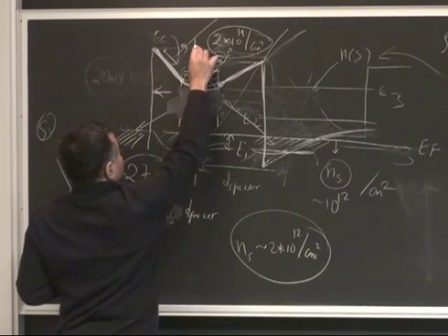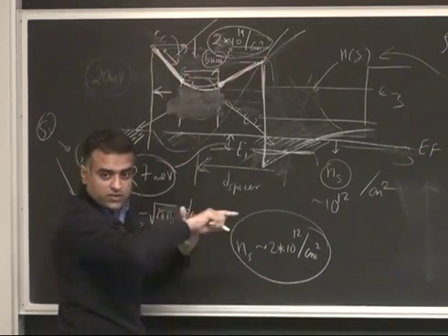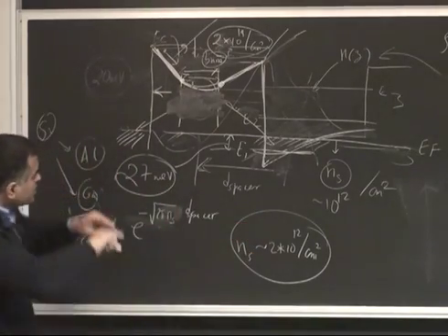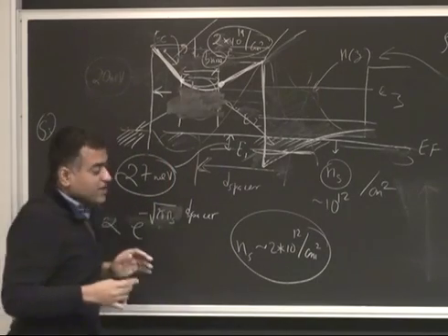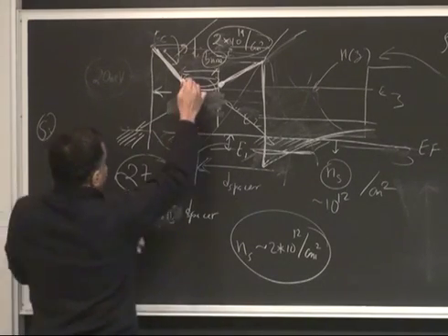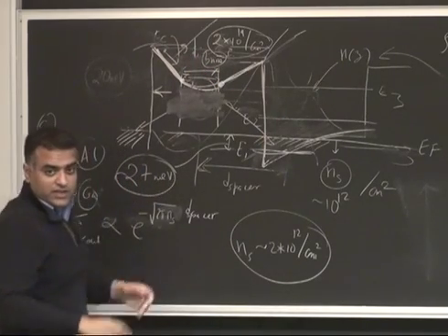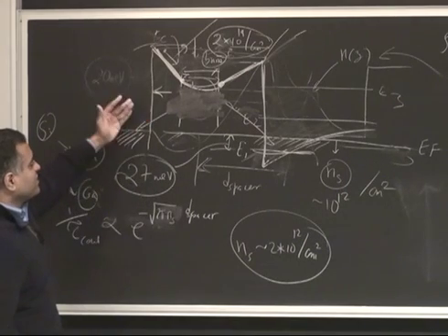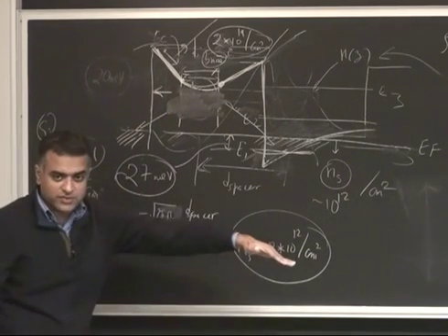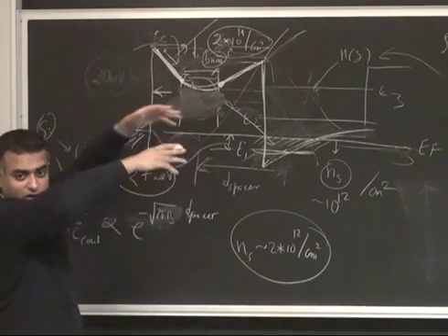These electrons are ionized, thermally in the band, so they are mobile and move in both directions. Part of them go there, part of them go here. But it will get harder, because the electrons now have to climb up. The thing about equilibrium is that in the end, the Fermi level has to be the same everywhere. That dictates what we got here. That's the end result of all that.